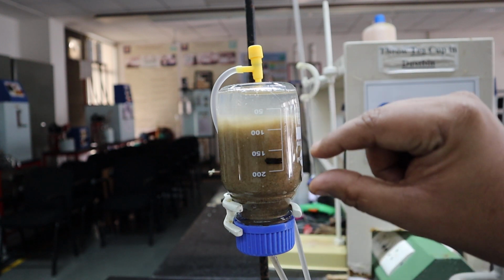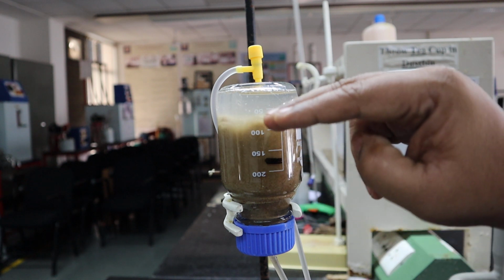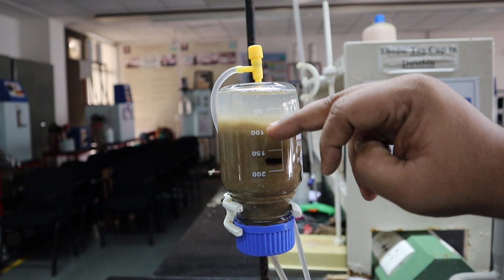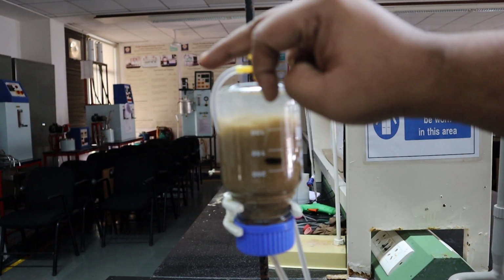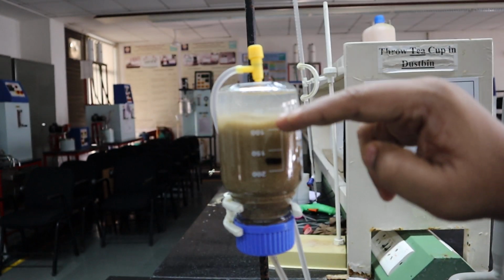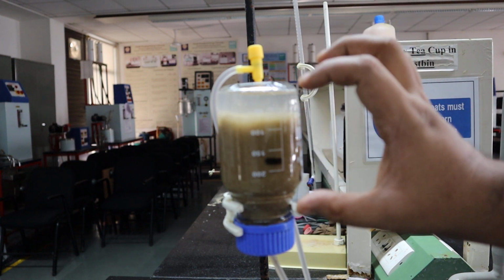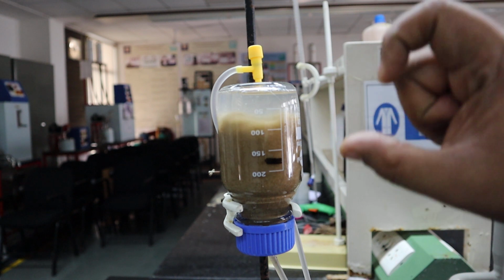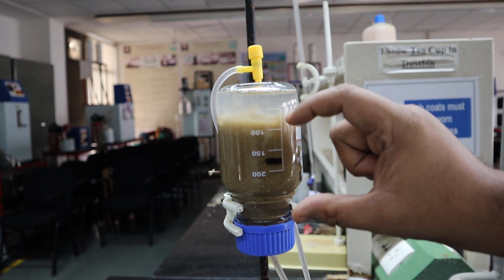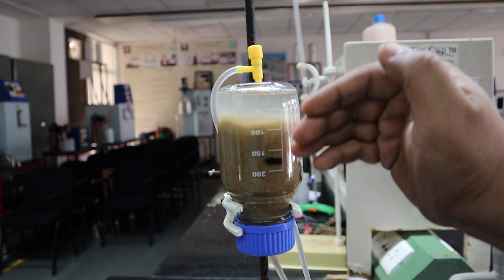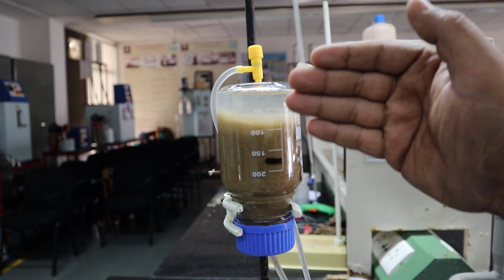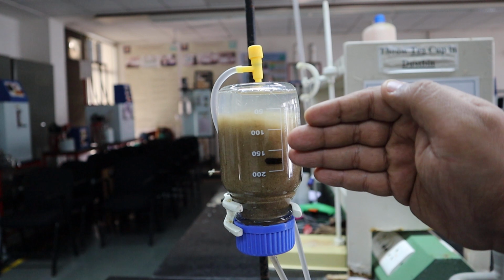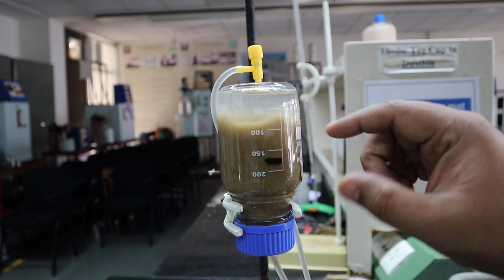So if you keep a velocity higher than the fluidization velocity, what happens? The particles will go to the outlet. Here I have maintained a certain velocity so that the entire bed is in the fluidized condition. Because of this, you can transport solids. Beyond fluidization, that's called pneumatic or hydraulic conveying.